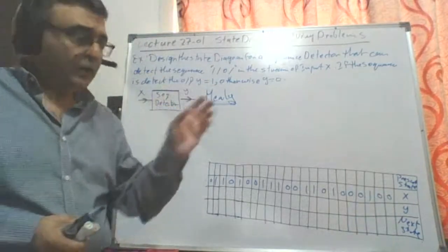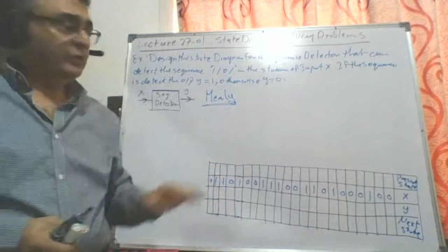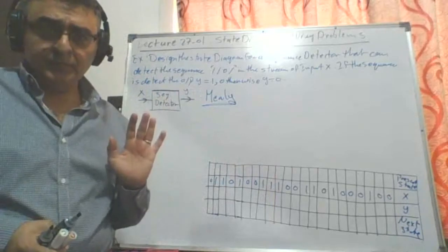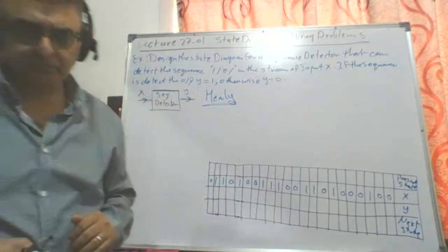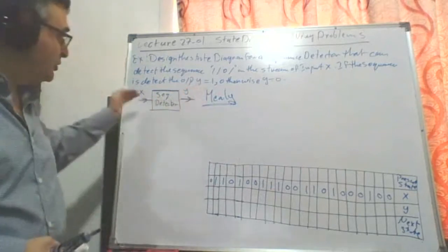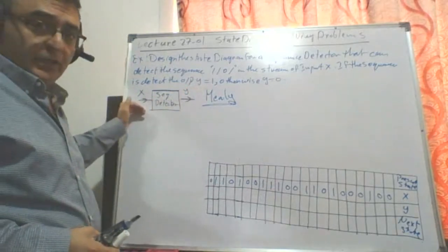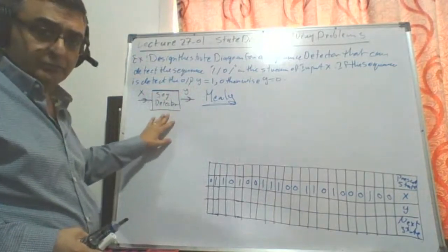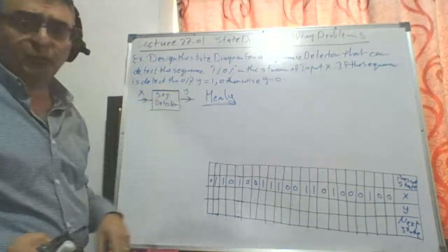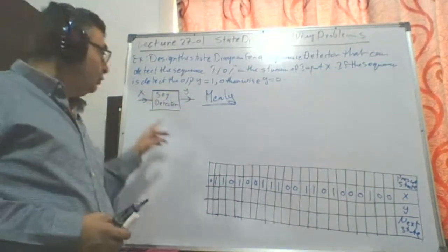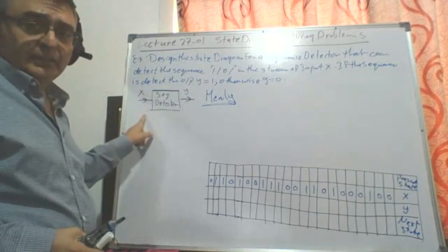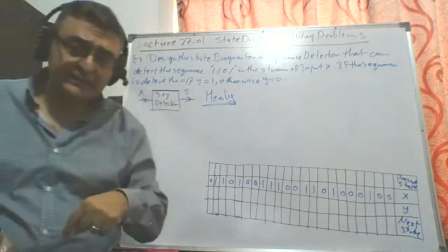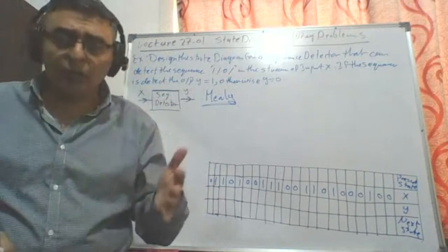So first of all, I want to know how the sequence detector works. The sequence detector is actually checking the history of X. X is provided as a sequence of inputs, and it is feeding the block, the circuit, and it should produce the output Y. Do you want only one value of X? The answer is no. I have to have a window of the history of X in order to know whether Y will be 0 or not.